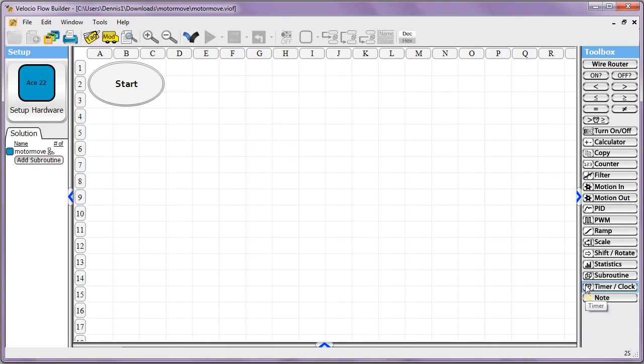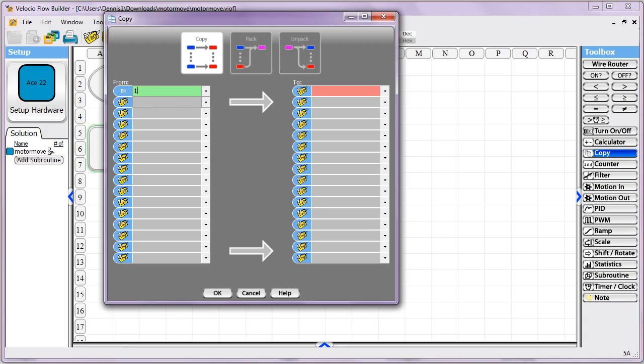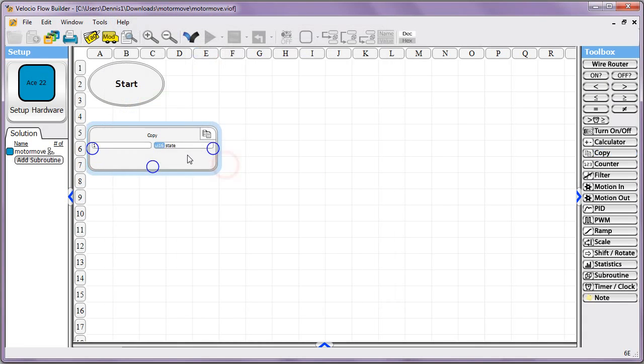In our other tutorials, if you go into the software tab under tutorials, you can see some other examples where we describe state machines, but I'm going to set this up as one. So first thing I need to do is initialize the state machine, and we'll make state a UI16 in this case.